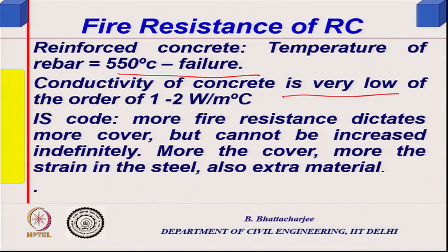Conductivity of concrete is very low, 1 to 2, and as I told you, more fire resistance dictates more cover, but it cannot be increased indefinitely. The more the cover, the more the strain in the steel, and also extra material, so cost will increase.